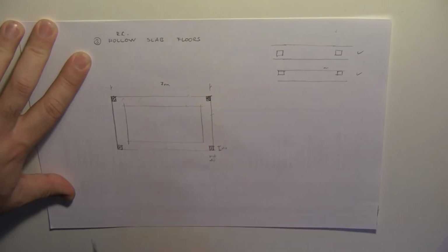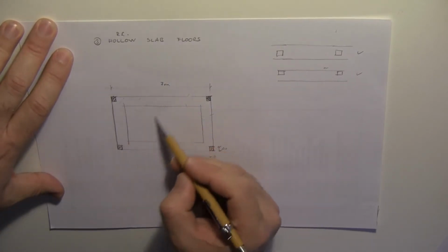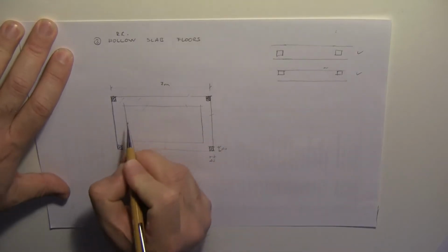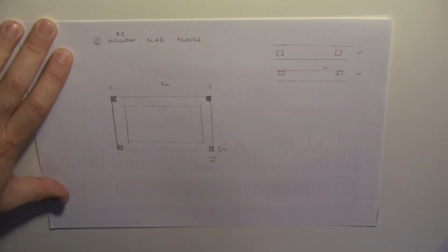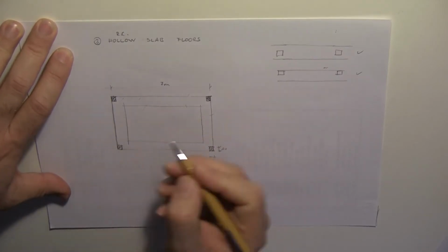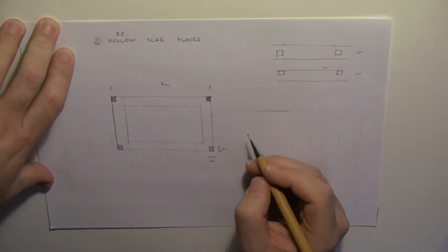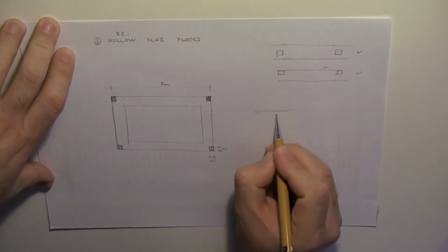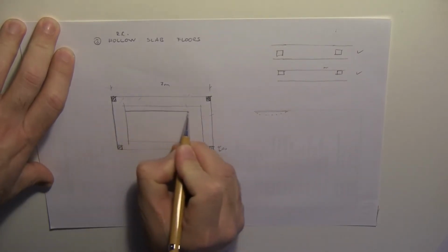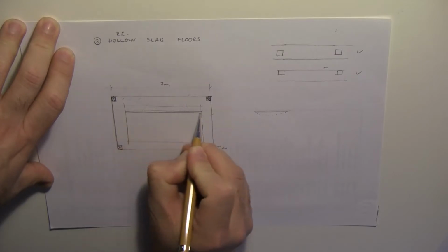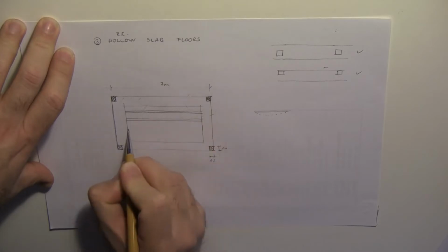Let's say that it is 7 meters in this example, and we do not want to increase the total weight of this floor. That's why we want to have a layer of concrete on top of these beams, which will be around 7 centimeters. But that 7 centimeters of a slab made of reinforced concrete is going to bend so easily. That's why in order to support it, we are going to add some secondary beams parallel to the long main beam directions. Like these.